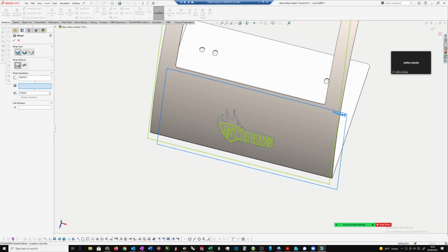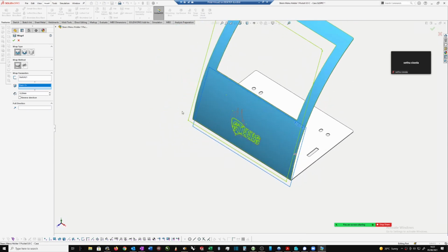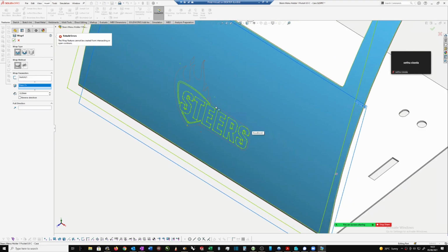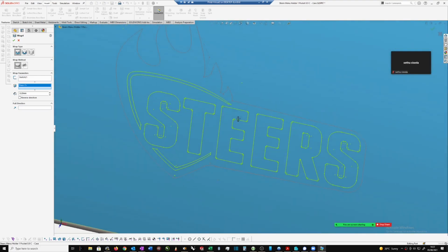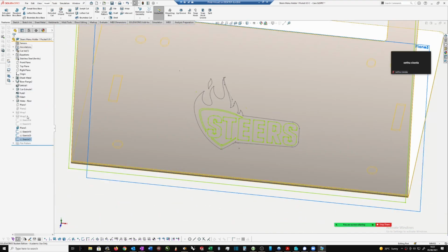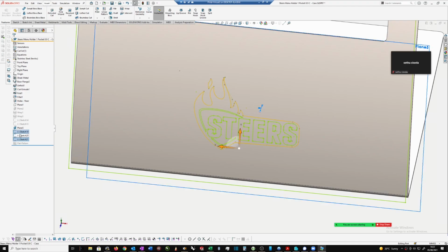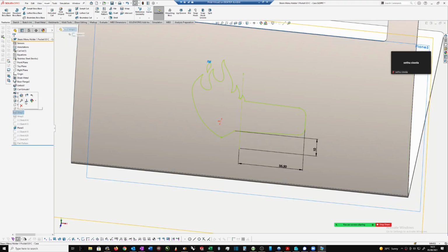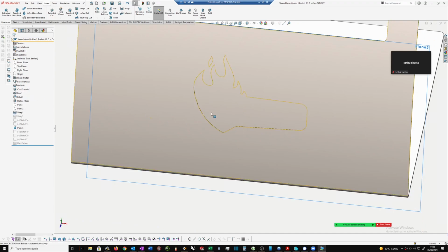So that one we're going to emboss. We want it to come out. So there's a problem with the sketch. I know what it is. That little line that you saw that I deleted comes from somewhere in here, and there's an open sketch somewhere. Never mind. So we'll have to just ignore those for now. So you've got the method. So that's the tricky bit, is making sure that your sketches are right and that they're properly joined.